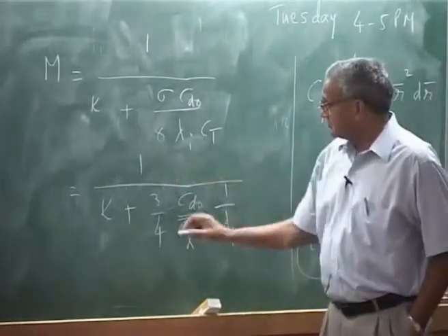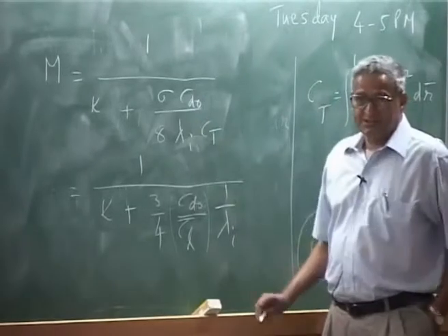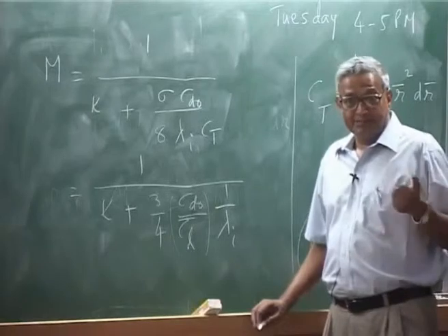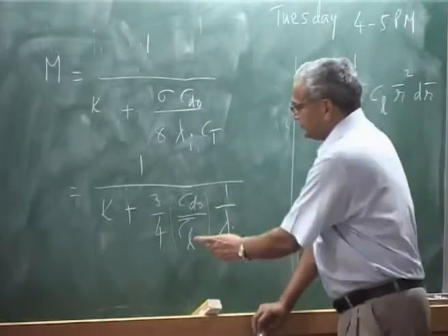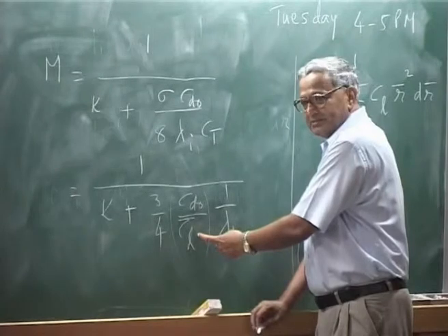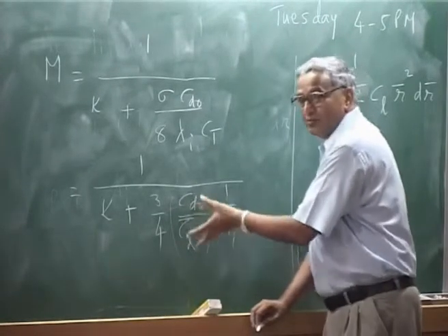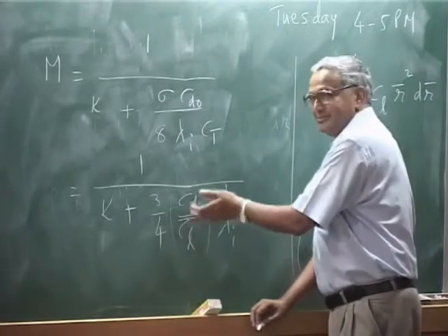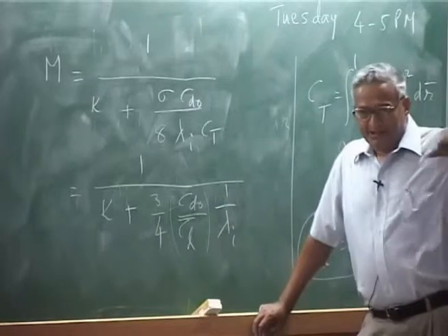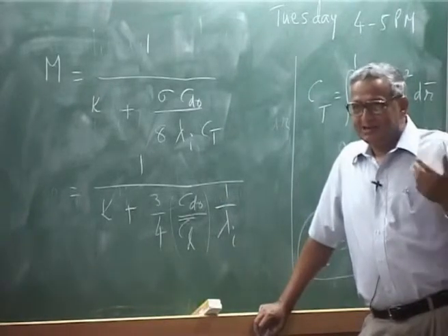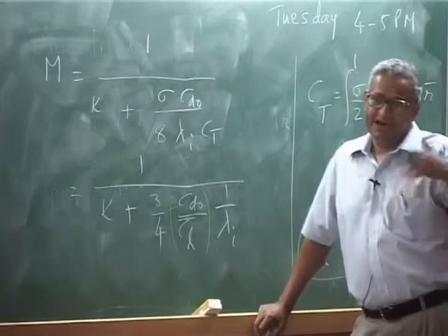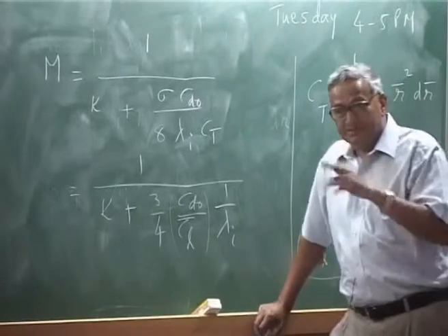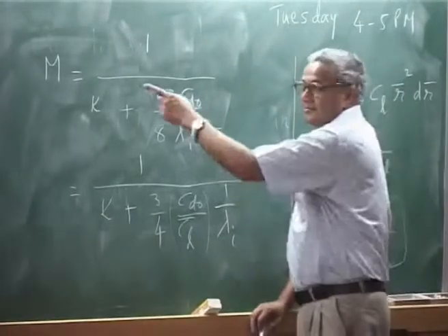Now, in this form, you have CD naught, which is the sectional profile drag, CL bar is sectional lift coefficient, you can take it, mean value, which is a sectional lift. So, what this form tells you is, if a rotor is hovering, the figure of merit I can improve if this quantity is small. Small means it should operate at CL by CD naught at a higher value. CL over CD must be high. If the rotor operates at a high CL over CD value, then your figure of merit is also high.